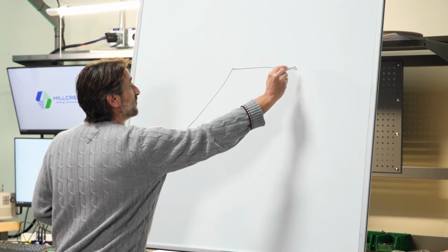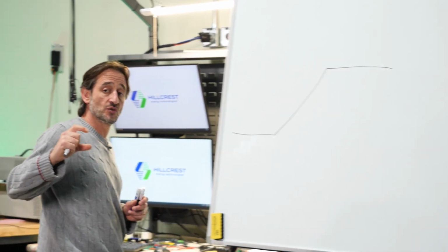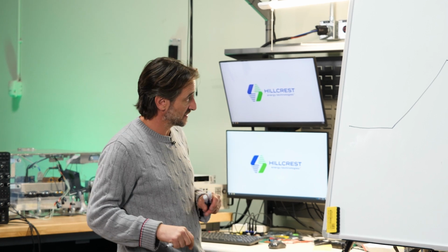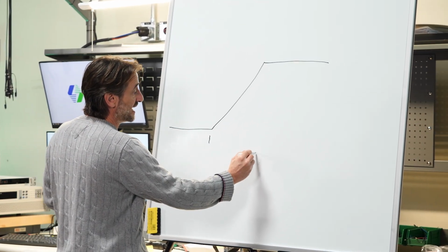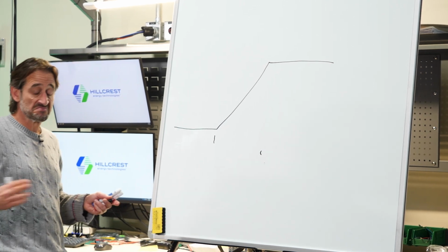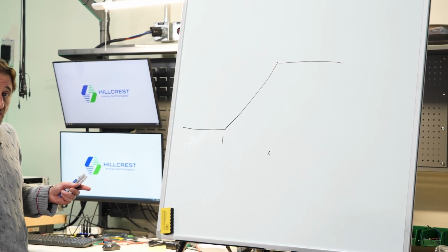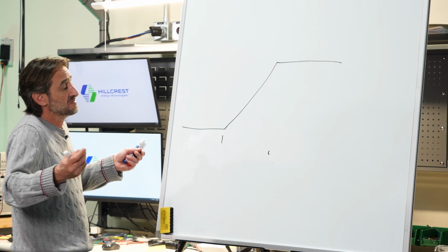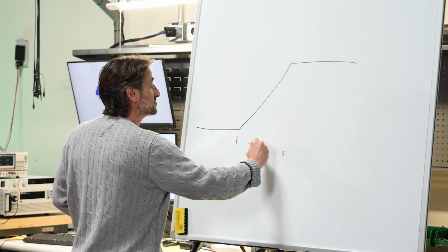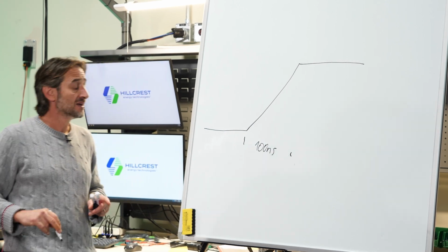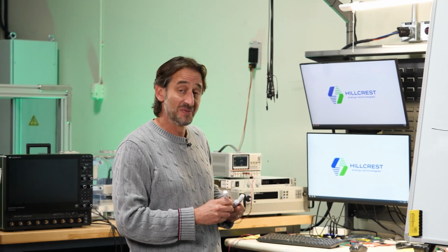When I turn it off, the voltage across the switch looks like this. It takes time for the electronics to actually open the switch, like we mentioned. This time could be as short as 100 nanoseconds. That's a really short time, but during this time there's a lot of heat being produced.